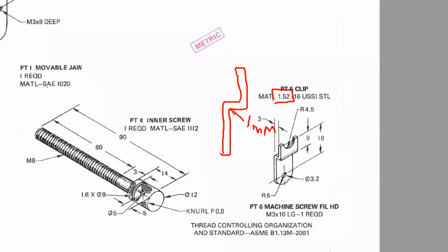It'll be concentric circles, right? The outside and the inside would have the same center point, but the radius on the outside would be this 1 plus the material thickness. So that would make that one 2.52. So you just add whatever this radius is to the material thickness to get the outside. The same thing would go here. A lot of times I see people just put the same size fillet on the inside and the outside, and that doesn't maintain a uniform wall thickness. It looks wonky there. So that's about the only thing you have there.